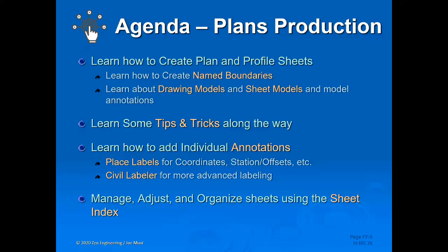You're going to learn how to place something known as a name boundary. Now, I apologize if some of you have already been playing around with the OpenRoads sheet creation tools and you're kind of familiar with some of this stuff, but I will definitely dive a little deeper into some of the settings to help you understand what they mean in case you weren't fully aware of them. So the first part is to lay out what's known as name boundaries, and then from there you create what's known as drawing models and then sheet models.